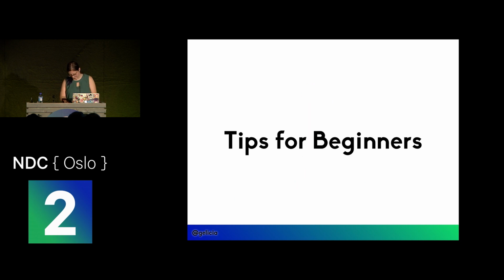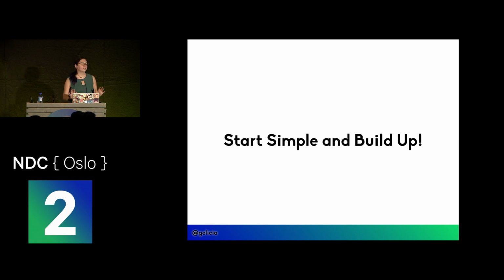So let's get to some tips for beginners. Always, always, always start simple. I help a lot with hackathons, and the biggest problem I see with groups that want to do their first hardware project in a hackathon is they have these beautiful, grandiose ideas, and I love them for it, but you want to stick with a sensor and a microcontroller. What can you do with that? Is it putting it in a box?